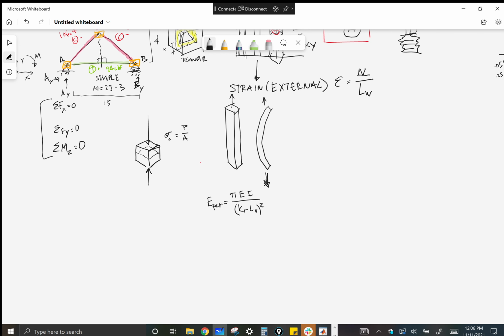And that's the whole, like when you get into radius of gyration, the square root of I over A, it's like how efficiently you're using the area, right? So it is shape, not just area. It's not the pure amount of stuff, it's how it's configured. But the simple way we've been conceiving of it is what you're saying, that the more stuff you get away from the centroid, the stronger it is about a given axis, right?